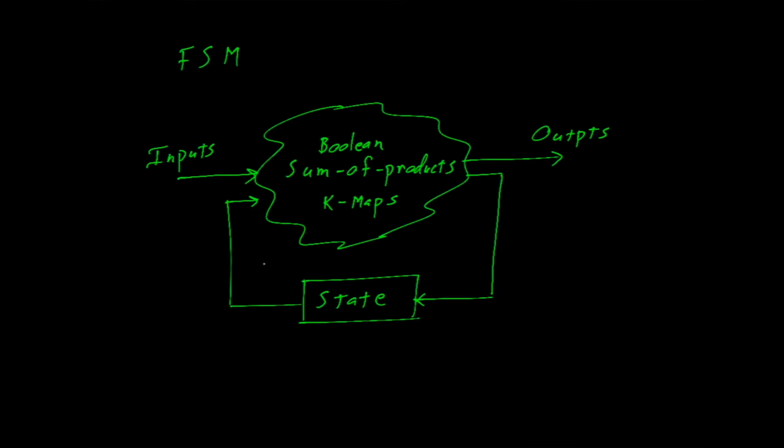If we're more precise, we would call this the state, and we would call this state next, with the understanding that the state registers are activated by clock, and the contents of state next will be transferred to state on the rising edge of clock. For our purposes, we'll assume that these state registers are the type D flip-flop.